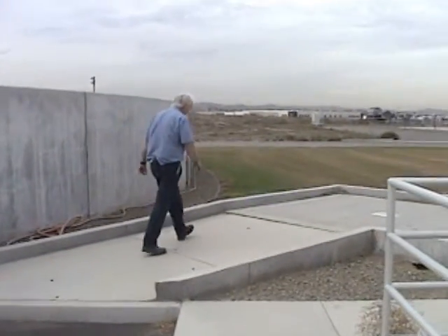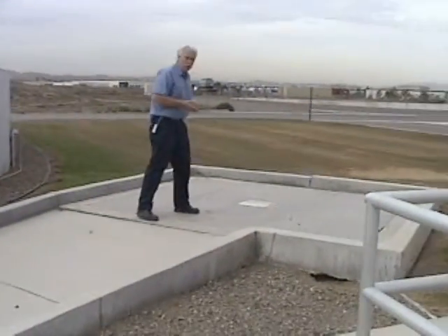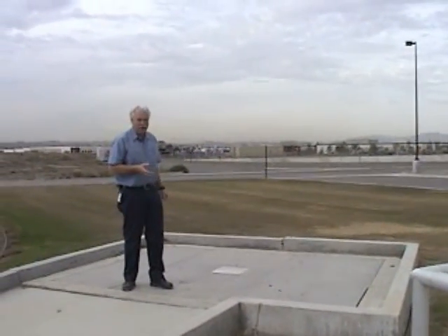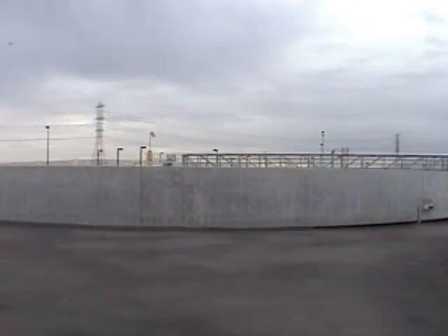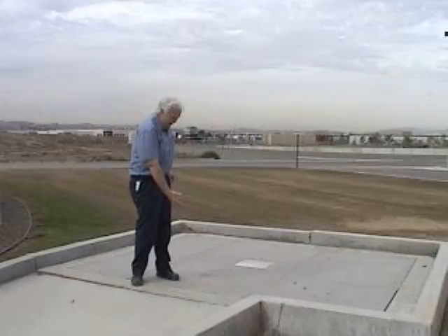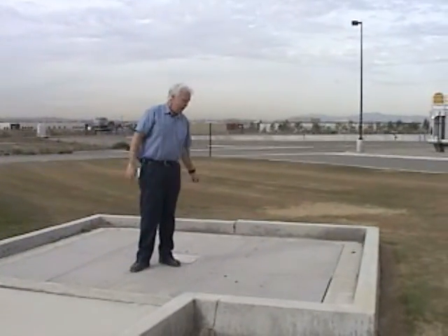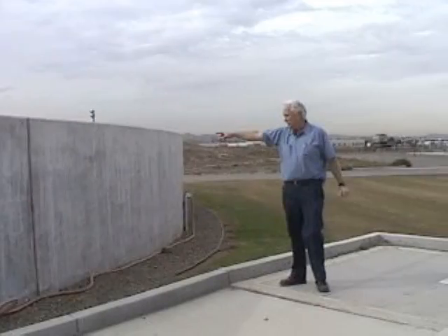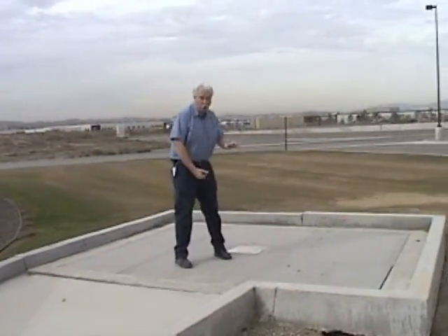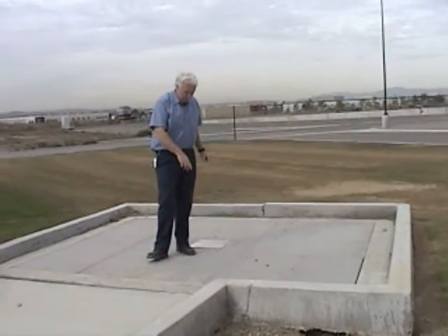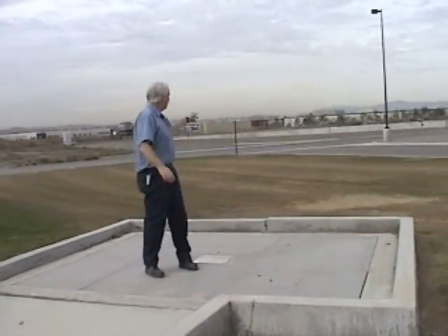What I'm standing on here, this is really important to understand how this operates. When we want to de-water a clarifier using pumps, because right now when we pull secondary clarifiers down before, we've used the RAS pumps to pump them out. But if you're in a situation where the RAS pump will not pump it out, this structure is where you would do it. All 4 clarifiers are fed into this tank. There's valves down below from each clarifier, and it's a big wet well. So if I wanted to pump this particular clarifier down, after I open the hatches here, I'd go down there, open that valve to this clarifier. This will begin filling with water, and then we can pump it over the wall back maybe to another secondary clarifier or a manhole in the street or something like that.